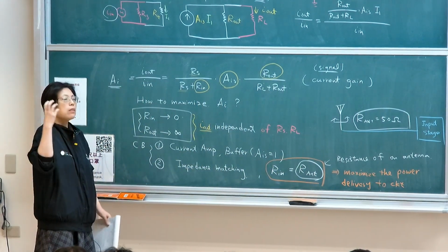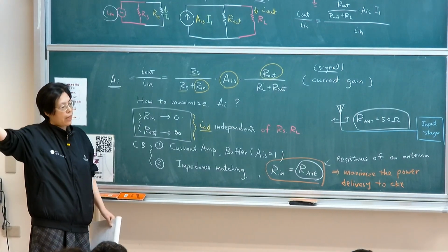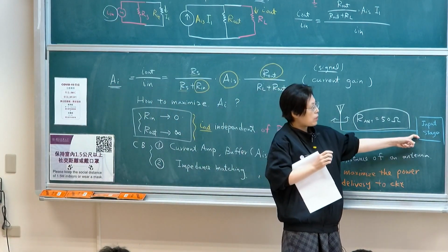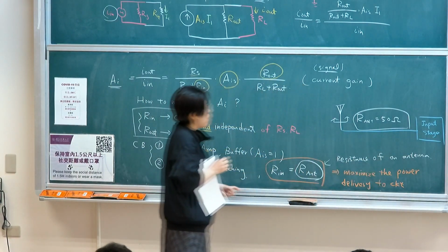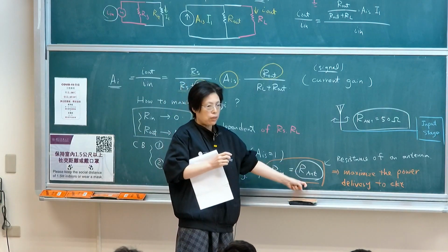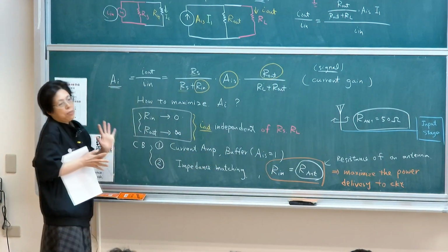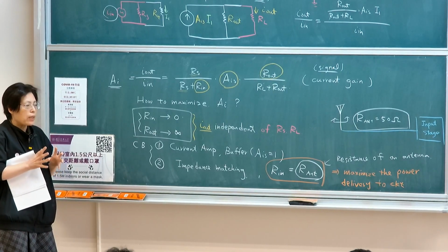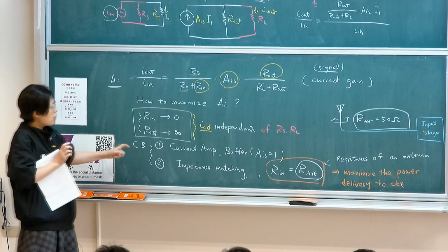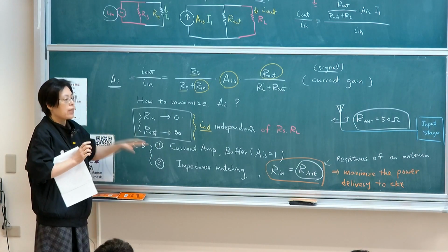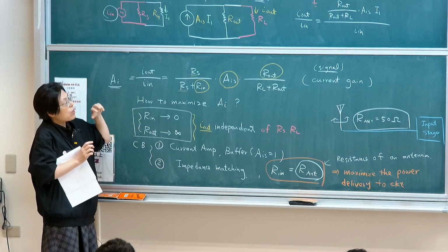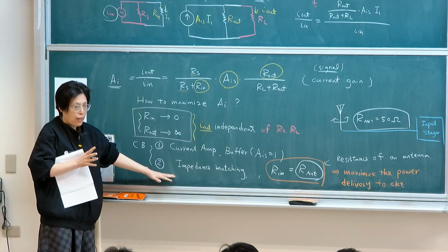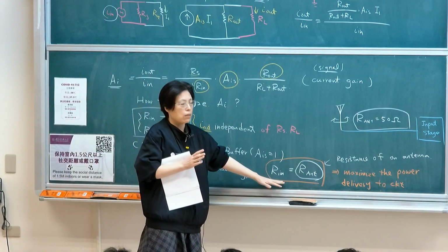Whatever signal you receive from the station coming into your antenna needs to be amplified by the input stage, which needs an input resistance that matches the antenna. This is typically relatively low, and you can adjust it. One of the key points is that the common base stage has low input resistance, and you can adjust that to a level which meets this.